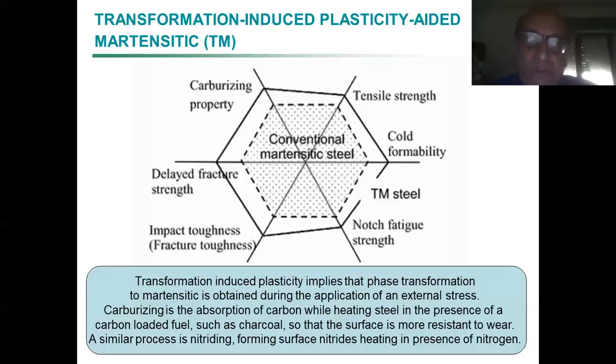Of course, you cannot do an infinite number of cycles, but you can measure a service. For example, you can consider that your structure needs to withstand 1 million cycles. During its life, you perform 1 million cycles at a low load, and you see if you undergo fracture or not. And so you see if there is a fatigue limit, despite the presence of the notch or not.